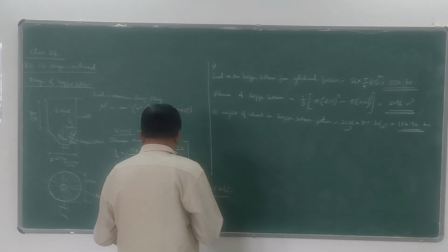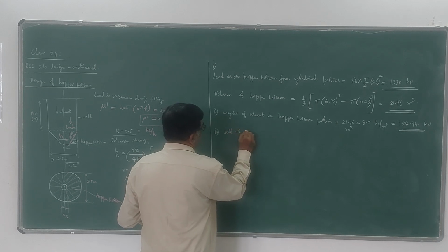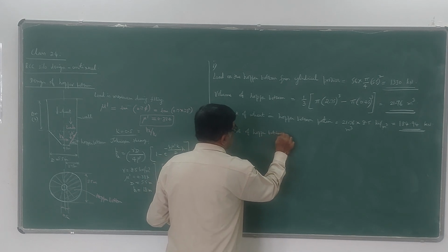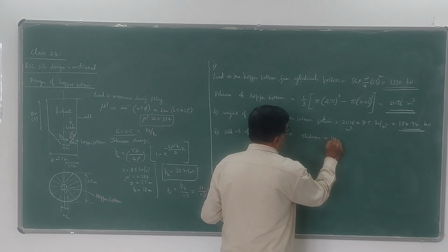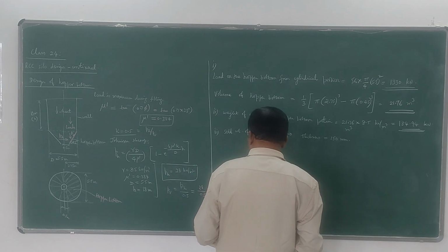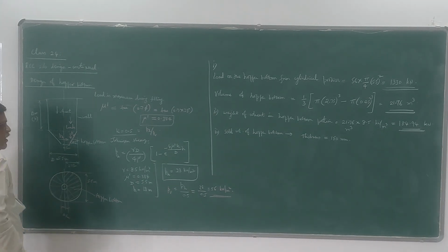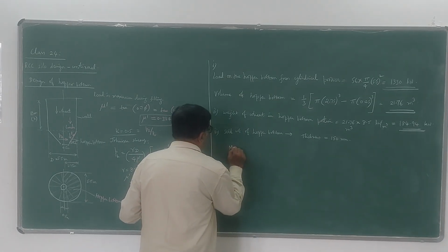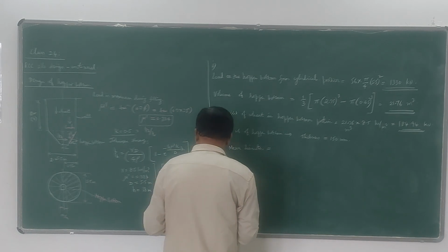Now we have to calculate the self weight. Self weight of the upper bottom. For that we have to assume thickness. So let us take the minimum thickness of the upper bottom as 150 mm. 150 mm is the thickness we are going to assume. Let us not consider the minimum or maximum diameter; I will take the mean diameter.